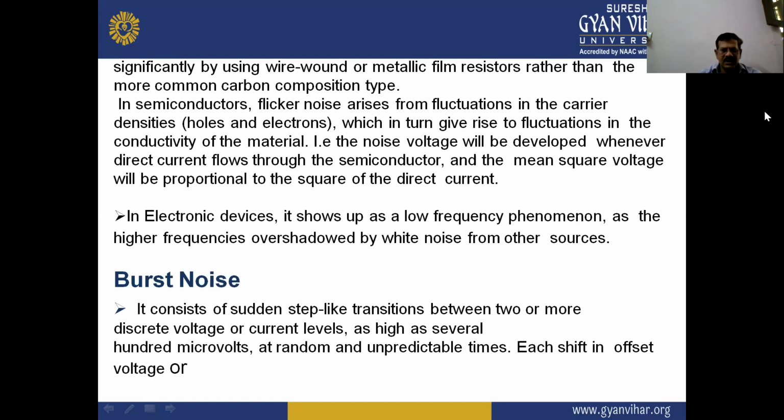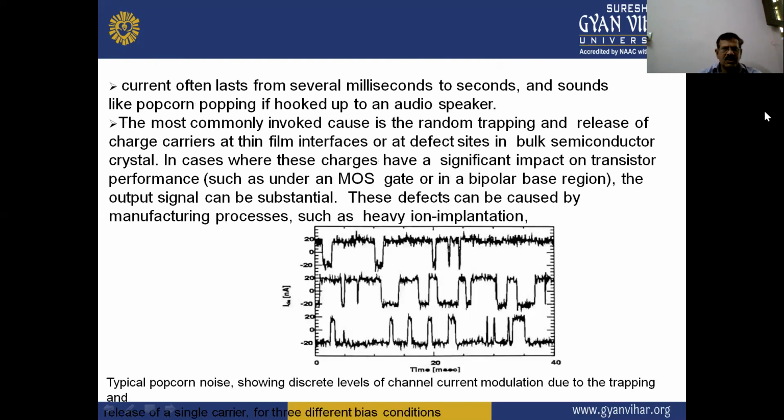Each shift in offset voltage or current often lasts from several milliseconds to seconds, and sounds like popcorn popping when hooked up to an audio speaker. The most commonly invoked cause is random trapping and release of charge carriers at thin film interfaces or at defect sites in bulk semiconductor crystal.